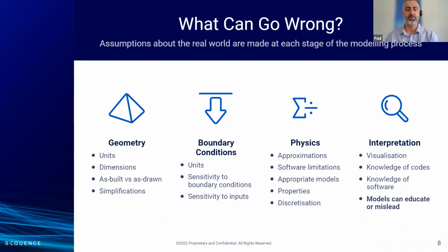So that leads us to boundary conditions. With one set of boundary conditions, a classic example for structures is a pinned connection or a fully fixed support. Depending on where you've set the extent of your model, the difference you get in deformations in a stress analysis, for example, between a pin support and a fully fixed support, can make a huge difference in terms of the overall result that you get. And normally the behavior is neither fully fixed or pinned, but knowing which one to use and the sensitivity to those boundary conditions is quite important.